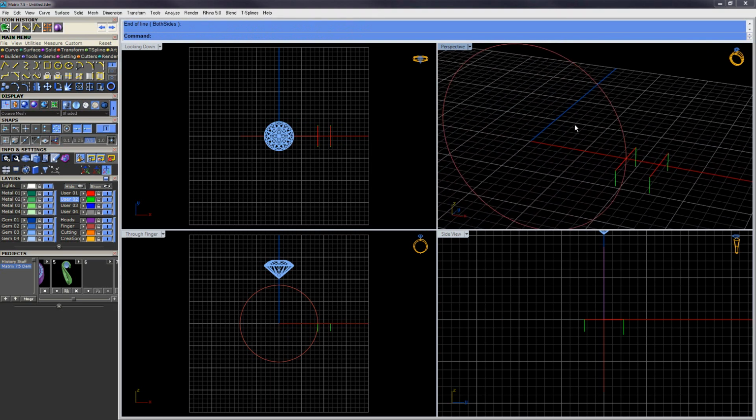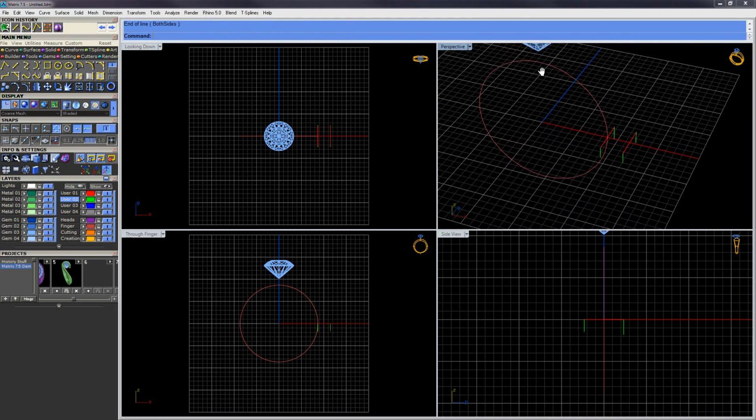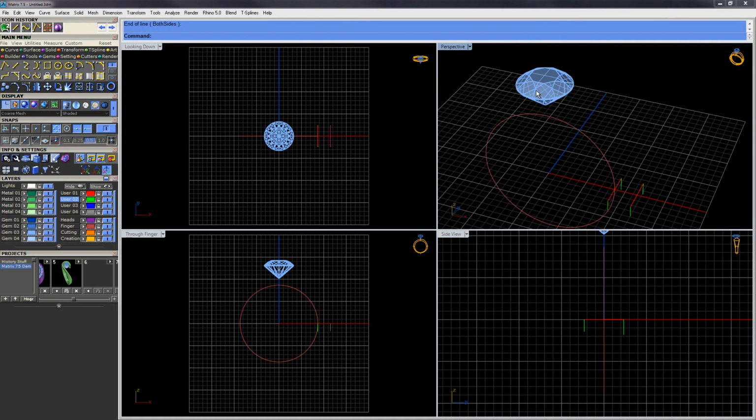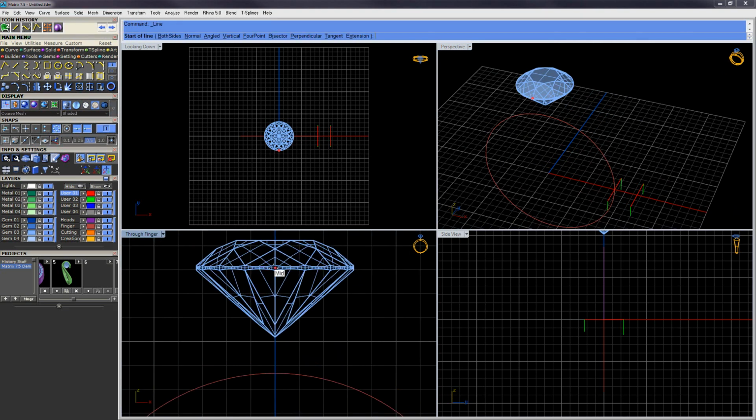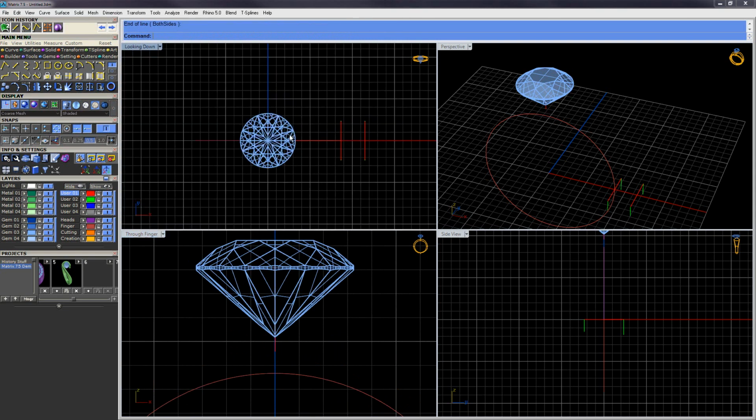So now that we have those created, we have to go ahead then and create the blend tick marks that we used up top. So there's any way that we can go about doing that. I can kind of use the same technique that I did to create the ones on the bottom, just give myself a couple of reference lines to snap to. So I think I'm going to go ahead and do that. And I am going to hold down Alt to defeat my O snaps, and again I'll set my height, and you can see the way that I drew that.